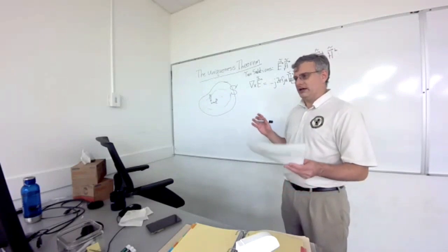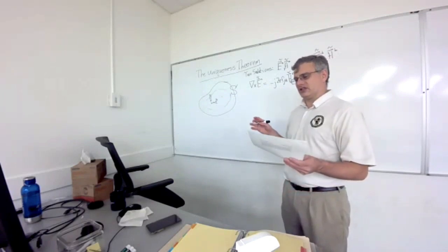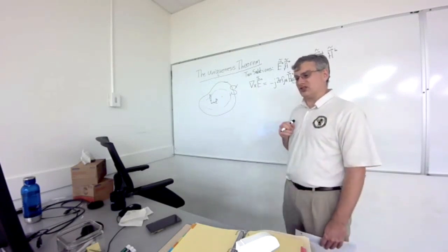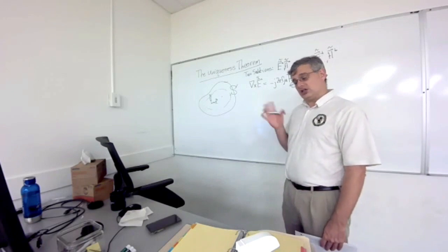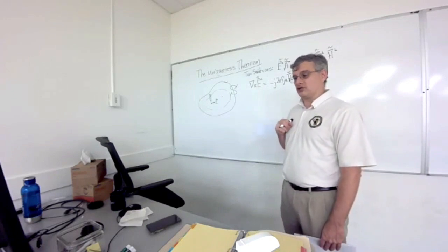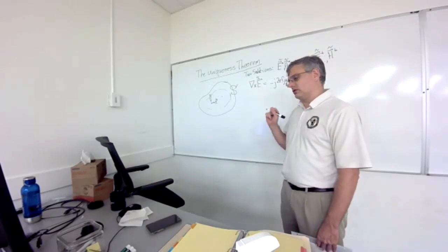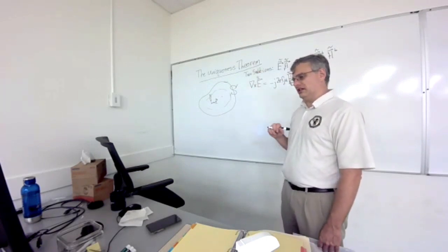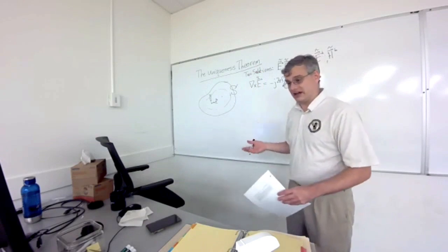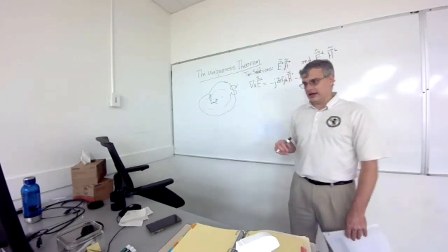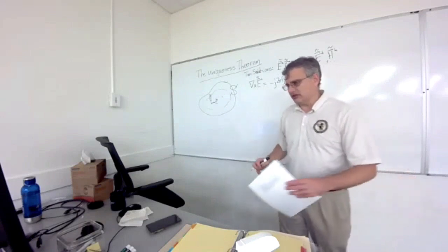It's a great analytical artifact for solving complicated problems, especially in scattering. I'm going to do the same thing for electric current, which doesn't exist, of course. We do that so that we have a general framework for uniqueness that includes even the artifacts we might want to introduce, like an impressed magnetic current.